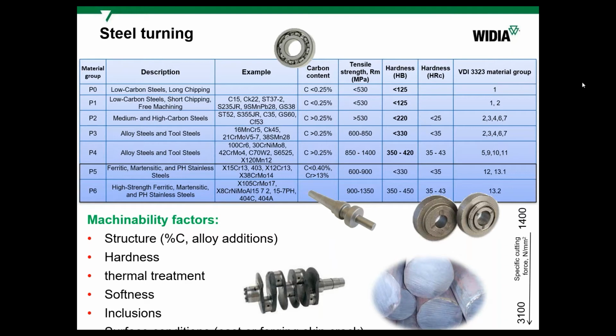Also, we talked yesterday very briefly about specific cutting force. Here you can see the range from about 1,400 to 3,000 Newton per square millimeter, or megapascals. You can put it in that formula and calculate cutting power if needed.